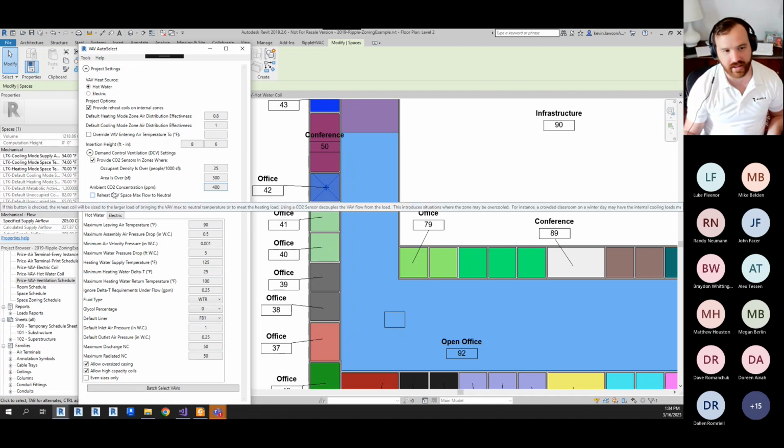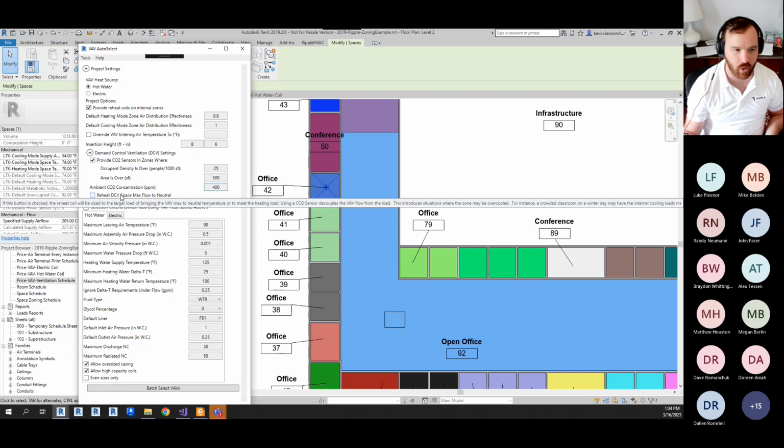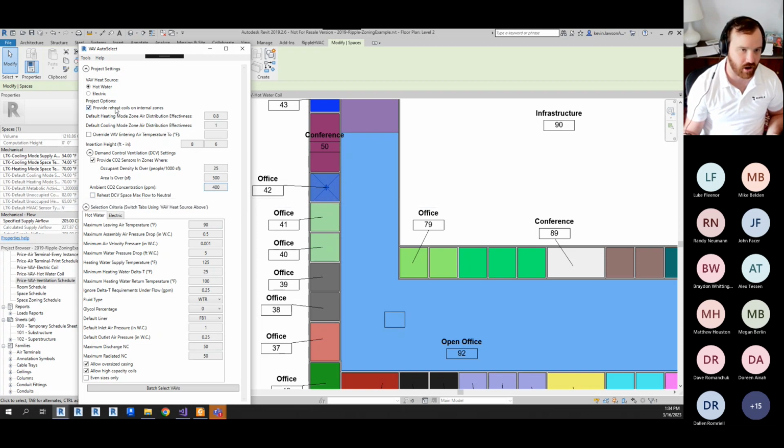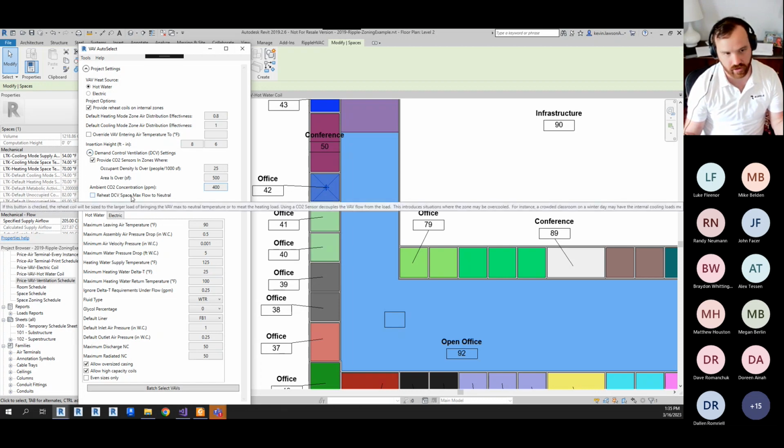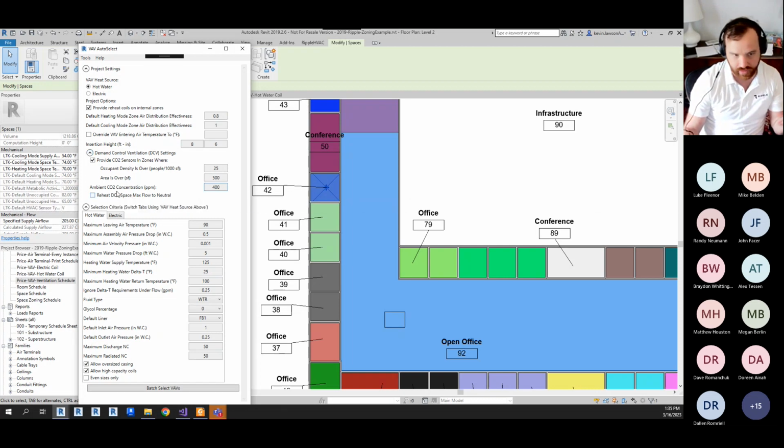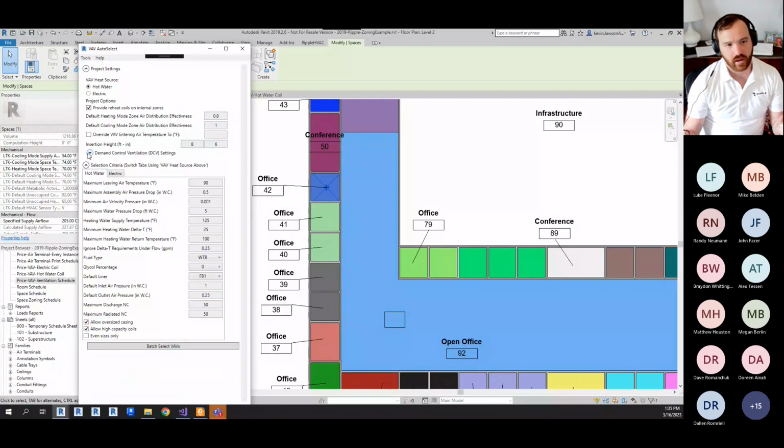It's kind of user preference. I've done this before, but I've also found that as long as I'm getting a reheat coil everywhere, I can at least temper that air and it's typically okay. It's really up to you. It's just a feature that you can have. Typically leads to bigger reheat coils, bigger VAVs, but at the cost of comfort, like everything we've been talking about.